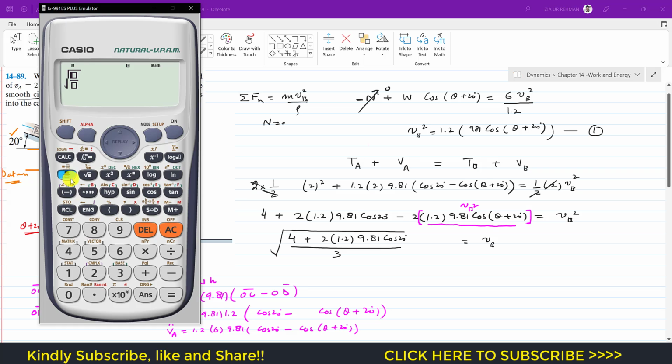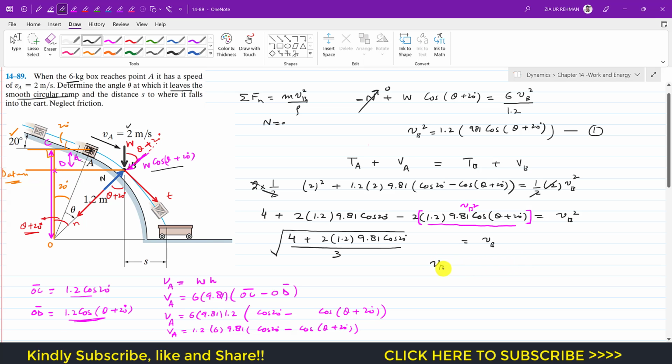Now VB is the square root of 4 plus 2 into 1.2. Let me take the square root: square root of 4 plus 2 into 1.2 into 9.81 cos of 20, divided by 3. This gives us 2.95. So VB, the velocity of the block where it will lose contact with the surface, at that particular point VB is 2.951 meters per second. This is that velocity which was required, and then we were required to find that theta.